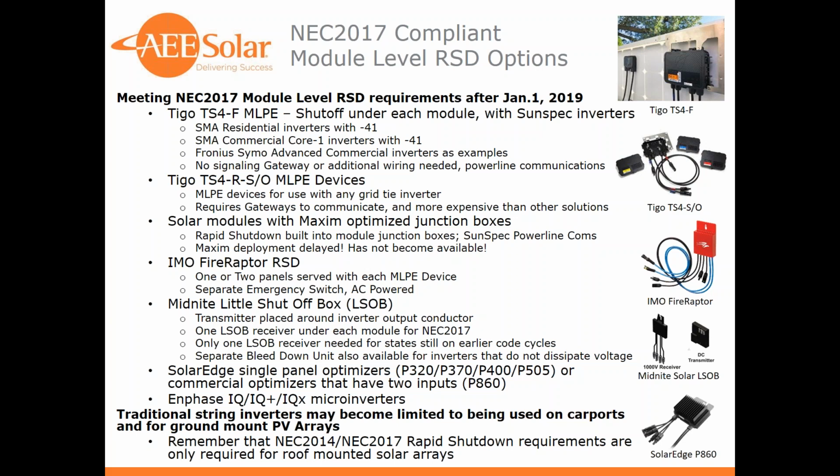Midnight Solar has been working on their little shutoff box. That was a very cost-effective solution for NEC 2014 for string level. For module level, you would need one little shutdown box receiver under each module. We have heard they're working on reducing the cost of that. We haven't heard too much more. Maybe we'll see something at InterSolar this year that would advance that product.